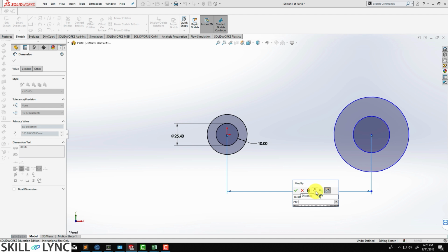Now the centers for the other two circles are going to be situated at a distance of 212.5 millimeters. Now we are going to select the inner circle on the other side, and this is where the crank is going to be located. So let's just click on that and type in a value of 43.75 millimeters. And as far as the outer circle is concerned, let's provide an offset distance instead of specifying a diameter, and put in a value of 20 millimeters.